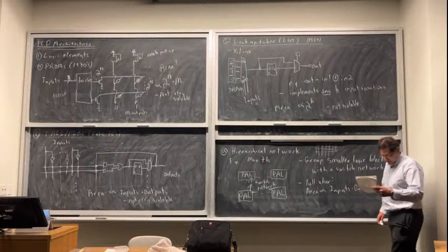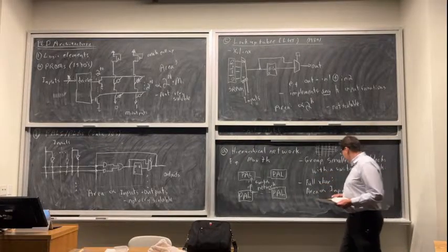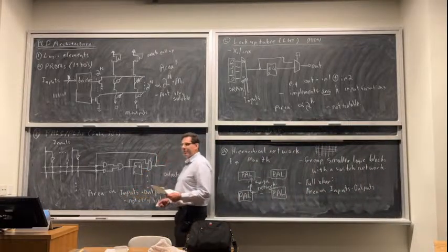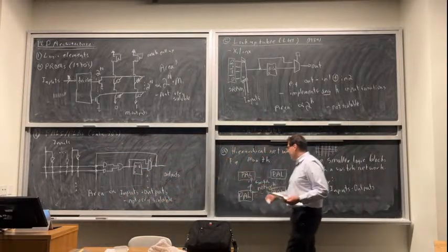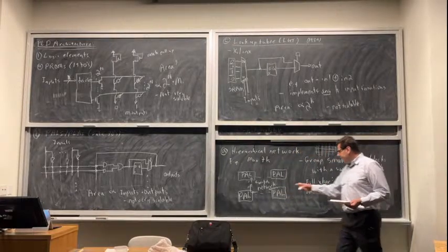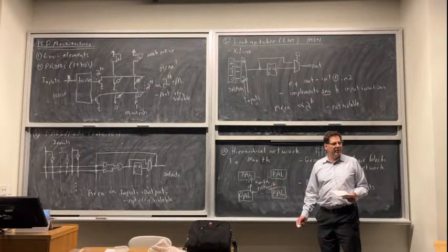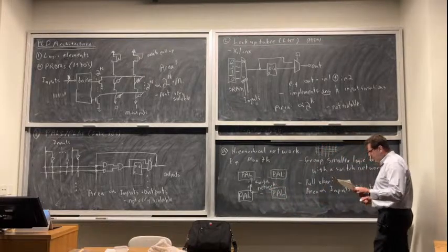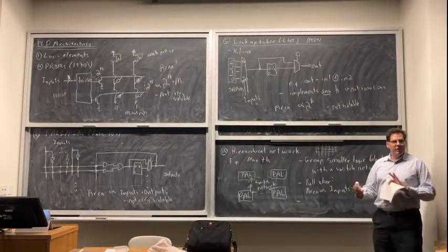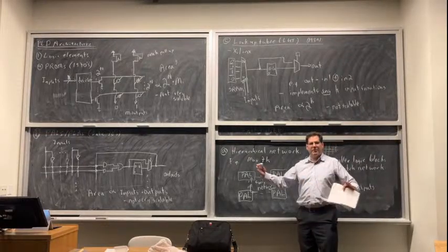So this is also going to limit us, right? We did this because we had this growth in this structure of inputs times outputs. So we're trying to defeat that. If we use a full crossbar, we wind up with, well, the growth is still inputs times outputs for the switch network. So we're not really much better off. So you can use full crossbars as long as they're not too big, but you can't just keep scaling a chip up and saying we'll use a bigger and bigger full crossbar. The area growth, again, is untenable.